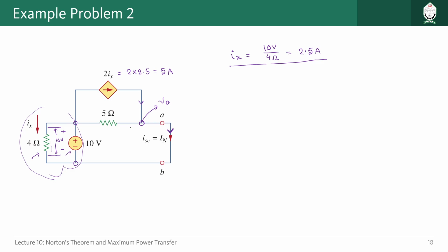Let us also assume that for this path, current is flowing in the direction of our VA. And we know for this node, the voltage value is 10 volt if we consider this one as the reference node. So from the reference node up to this one, the voltage difference is 10 volt. So we can say this particular node has 10 volt.